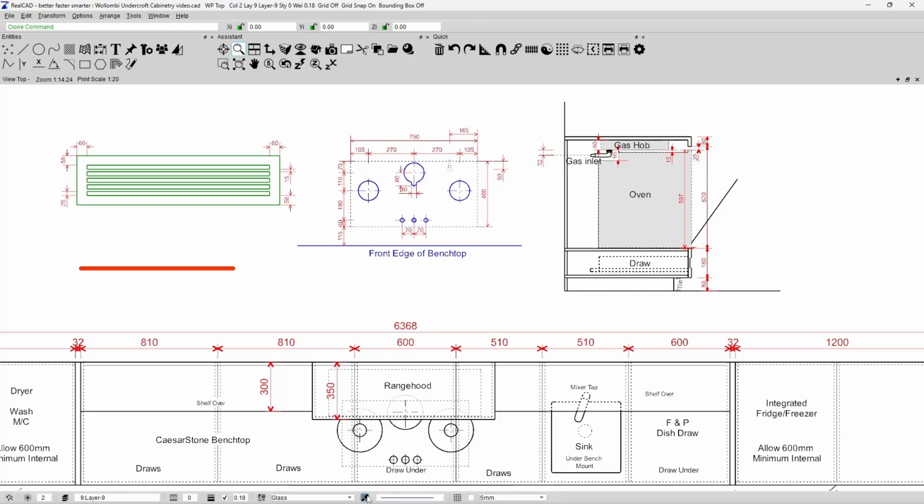This option allows you to clone the settings of any entity that's already drawn. If I select this and I click on this line here, you will see it has made the current settings the same as this line. So it's red and it's color 14, it's layer dimensions, line style 0, and line thickness 2.5.